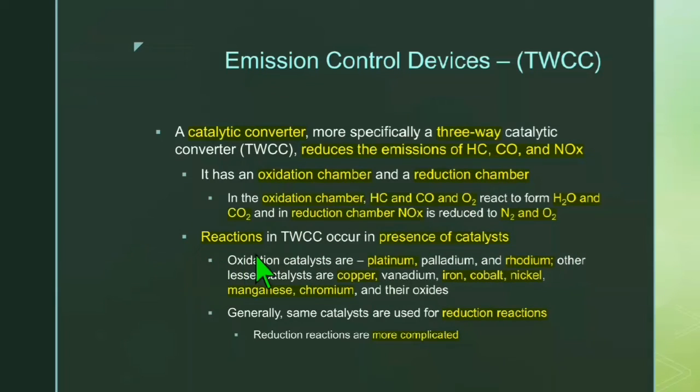Reactions in TWCC occur in the presence of catalysts. Oxidation catalysts are platinum, palladium, and rhodium. Other lesser catalysts are copper, vanadium, iron, cobalt, nickel, manganese, chromium, and their oxides. Generally, the same catalysts are used for reduction reactions. Reduction reactions are more complicated.